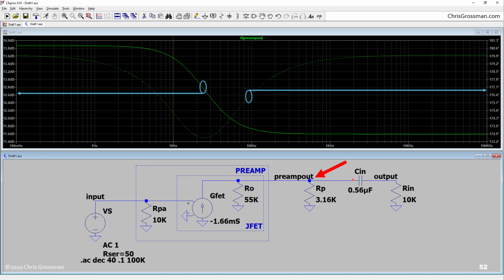But what's going on is at very low frequencies, this capacitor essentially disconnects this resistor, so we just have these two resistors operating as the load. And remember, we calculated like 14.5 dB, and we're getting here 13.9. So we were close. So that's why I did that other calculation, to show you what's going on at low frequencies. And then as we come up into the passband, this one's in parallel now, and so the gain drops, and this is what we got. And it's actually expected. So the key question is, what does this thing sound like?